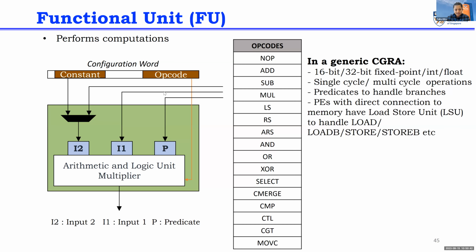And if the PE is directly connected to the memory, in addition to the arithmetic logic unit and multiplier, there will be some sort of memory handling load store unit, which will perform memory operations like load and stores.